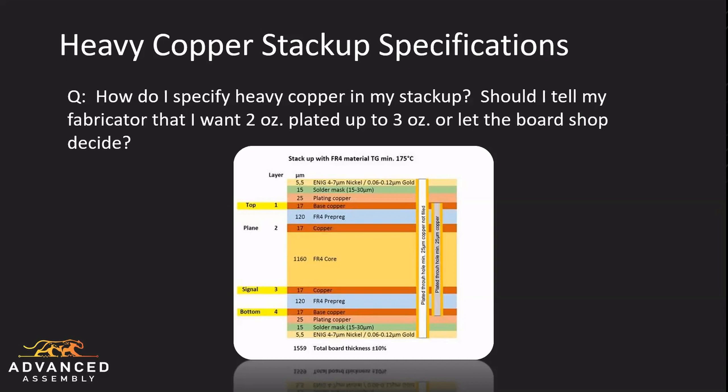Well, obviously now in today's world, 4 ounce copper layers is kind of common and they can be pulled off the shelf. But typically if you need something that's 2/2 that wants to get plated up to 4/4, there's a significant amount of processing that's involved with that. Not only the plating, but plating inner layers is very tedious, and then also actually etching those as well.